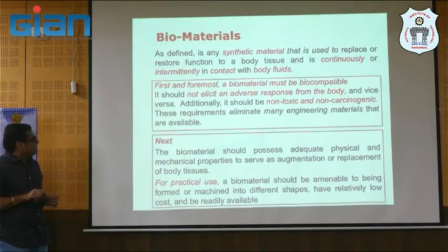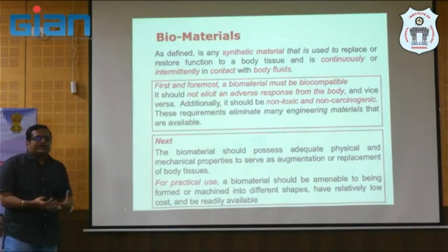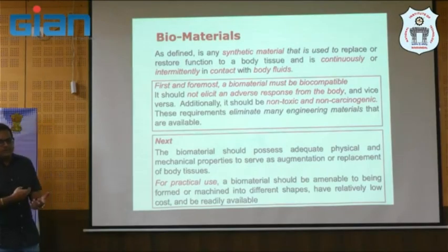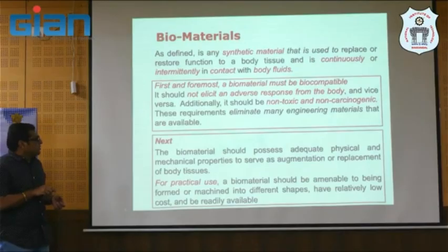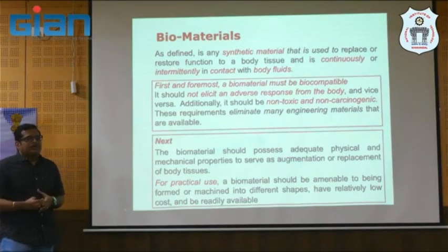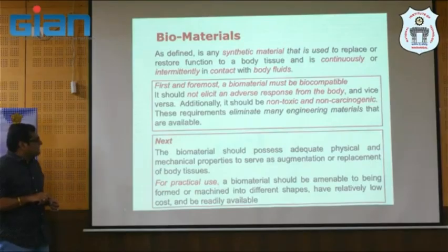What is biocompatibility? It should not elicit any kind of adverse response from the body, or vice versa. Once you put the biomaterial inside the body, it should not create any toxic environment. It should be non-toxic and non-carcinogenic, meaning it should not create anything cancerous inside your body. Because of these stringent requirements, the majority of our engineering materials may not be qualified as biomaterials.